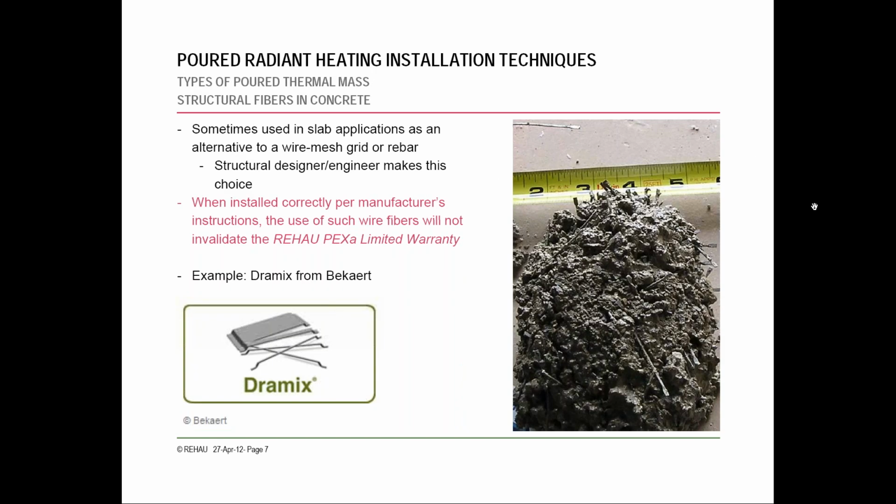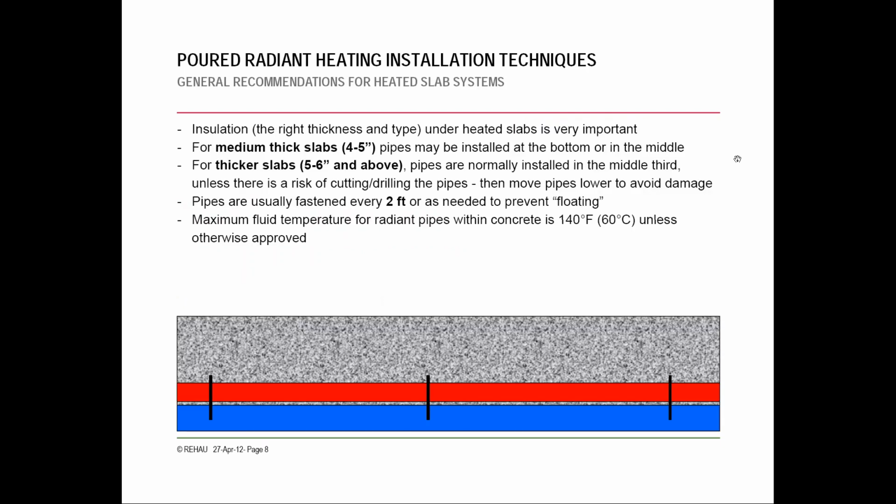Sometimes concrete, especially nowadays, uses different mixtures or different fibers to keep it strong as opposed to wire mesh and rebar alone. Those will not have any effect on the PEX. You should check with the manufacturer specifically, but most common PEX nowadays will have no issue working with additives to the concrete.